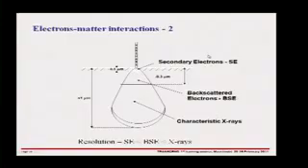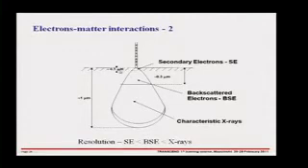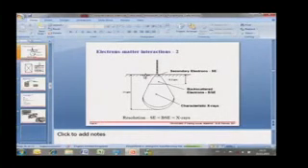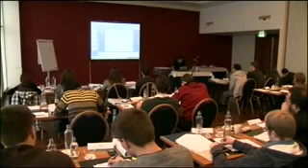But according to the different energy of these signals, this will be the depth from which you can detect those things. So secondary electrons, which I'll explain more in a minute, are quite low energy compared to the electrons coming in here, and therefore they can only be detected from the very near surface regions of about, that's completely wrong there, because it's way, way less than 0.1 micron. 0.1 micron should be about, for backscattered, it should be about 0.101 micron. Better make that alteration now. Sorry about this.